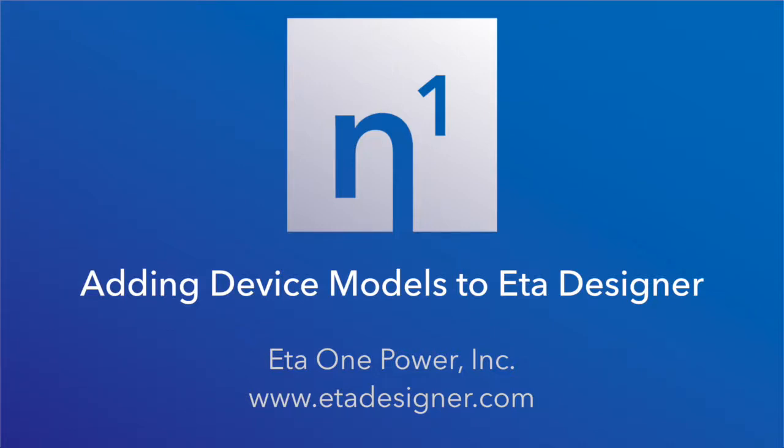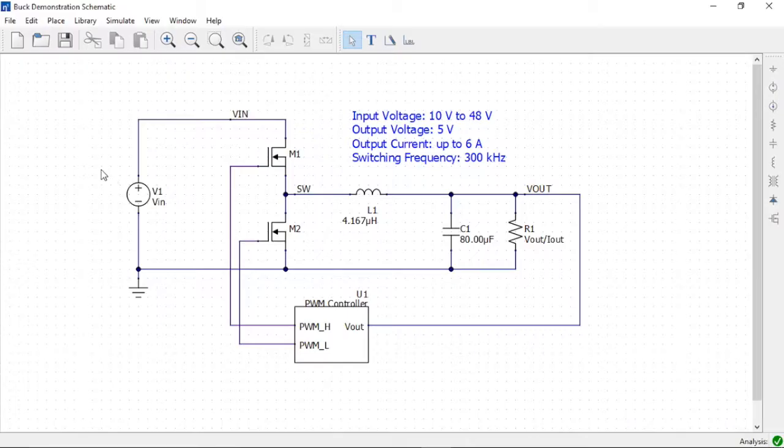In this video, I'll show you how you can add your own device models to your Eta Designer projects. We'll start with a simple closed-loop buck converter. While the converter simulates fine, we need to add accurate device models to calculate efficiency. The power transistor and inductor we'd like to use aren't in the master library, so we'll have to add them